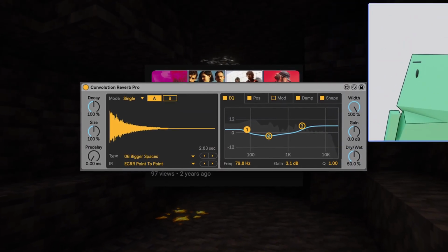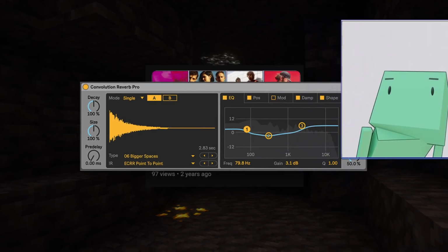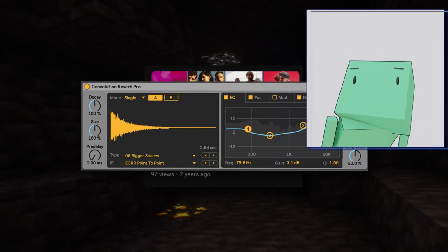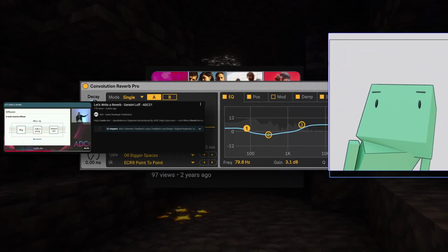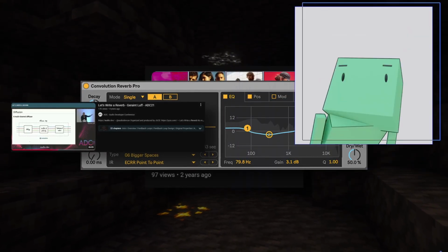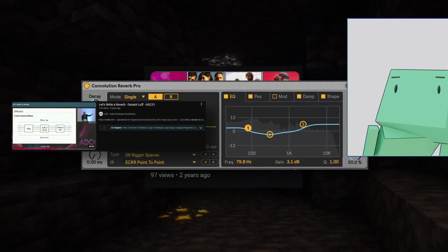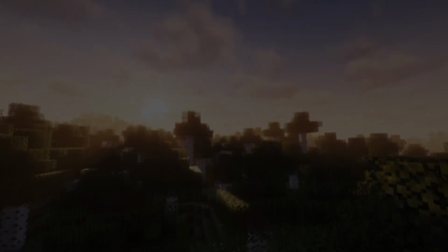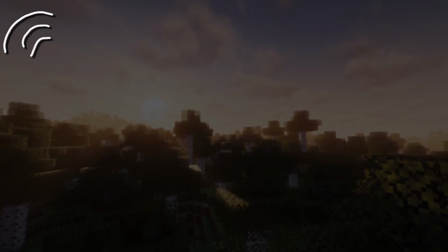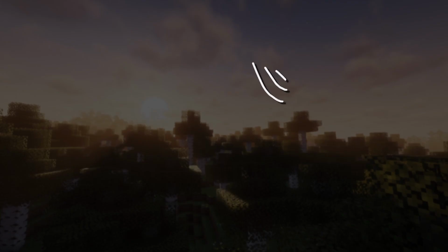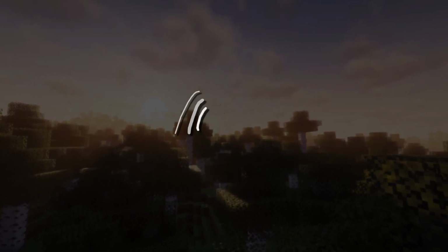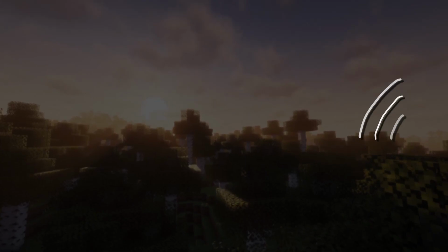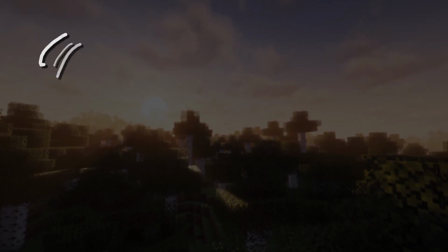And as cool as convolution reverb is, it is kind of hard to get up and running, especially with all the math. And so as an easier algorithm to break into a reverb design, I decided to pick the one proposed at the Audio Developer Conference back in 2021 by Signalsmith Audio, which is the design that we're going to use today. The basic structure of it follows the idea I presented earlier, reverb just being a barrage of reflected sound waves or really fast echoes. These echoes are also modulated and have lower and or higher frequency contents, as some frequencies from the reflected sound waves take longer to get back to the listener, while others are lost entirely.